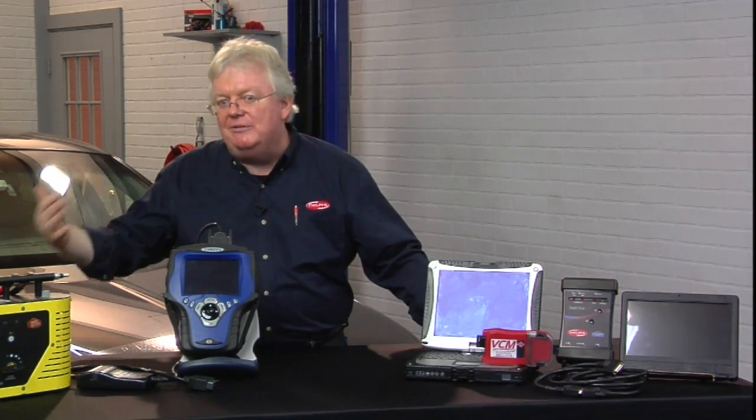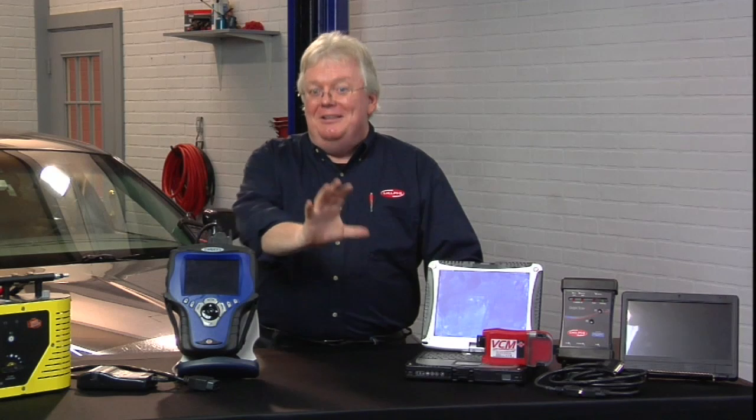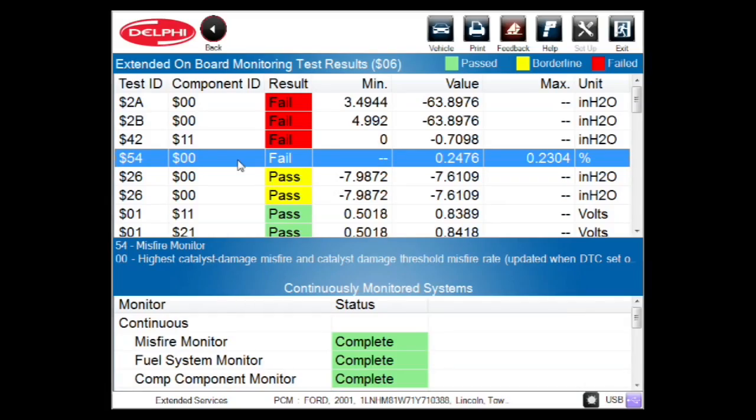They may have some additional services done later, or you may need to explain that these things existed before I fixed your misfire. I click on this last one that failed, and guess what? I've got a misfire monitor, $54. It's saying it's bad enough for the cat to be damaged. At some point in time, we kept running this hard and we smelled the sulfur smell from a lot of unburned fuel going into that catalytic converter. We're pretty sure we'd probably damage this catalytic converter. I'm sure the light would start flashing at some point and we'd finally set a code, hopefully.